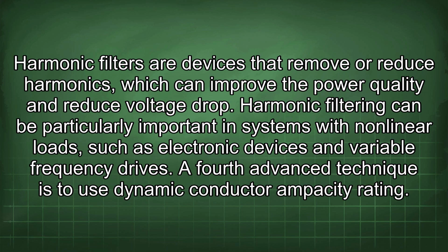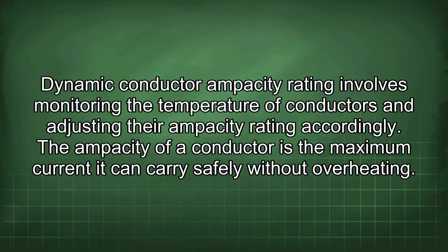Harmonic filtering can be particularly important in systems with nonlinear loads, such as electronic devices and variable frequency drives. A fourth advanced technique is to use dynamic conductor ampacity rating. Dynamic conductor ampacity rating involves monitoring the temperature of conductors and adjusting their ampacity rating accordingly.